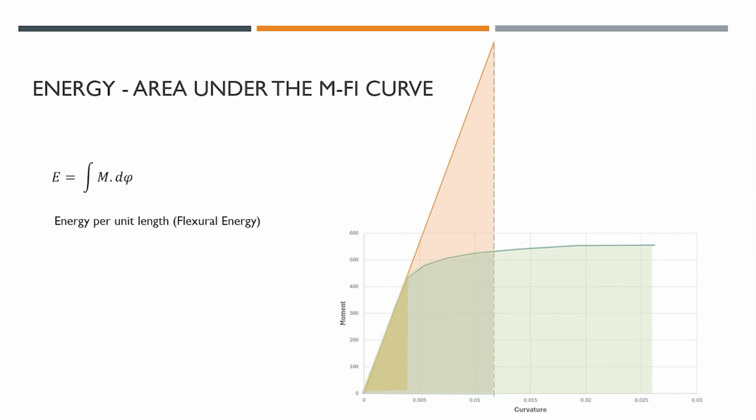So that's the elastic strain energy, which is before the yielding. That's the equivalent energy if it was elastic all the way, and that's the total actual strain energy under the curve with the ductile behavior. So that's what we are trying to show.